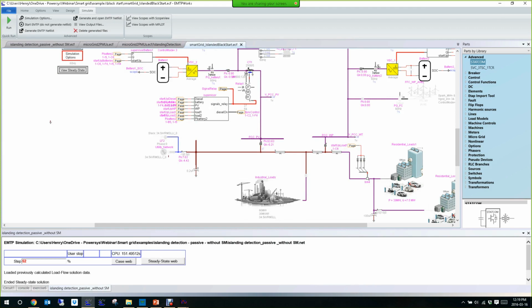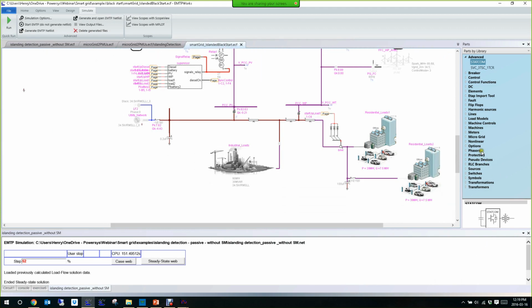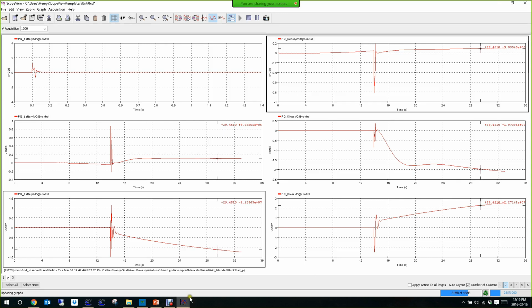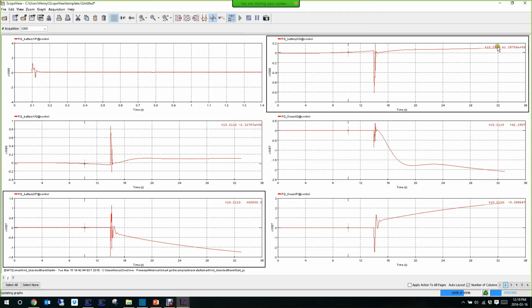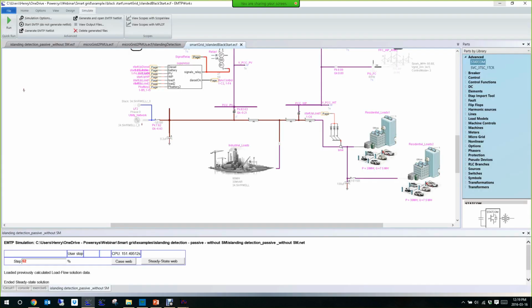Then we reconnect to the line and we reconnect the load. It's too bad I didn't run the simulation for long enough, it's my fault. But the most difficult part is really this one, synchronizing the machine. After that, everyone will produce for the load, and our system is islanded but operating. And you can reproduce some faults, load shedding, and see how the network reacts.